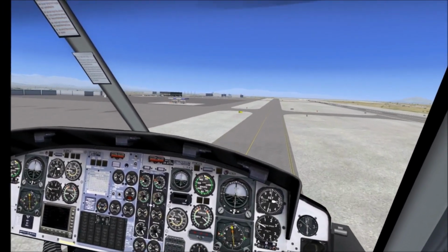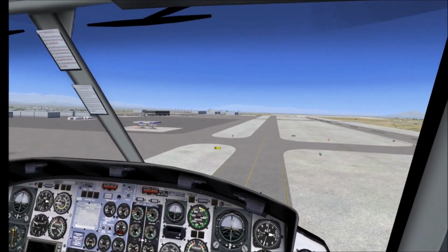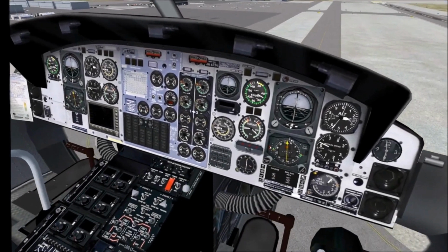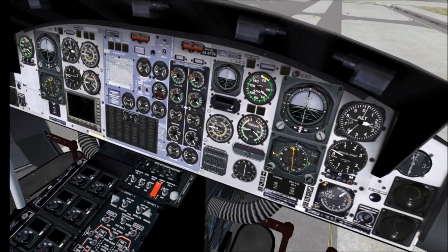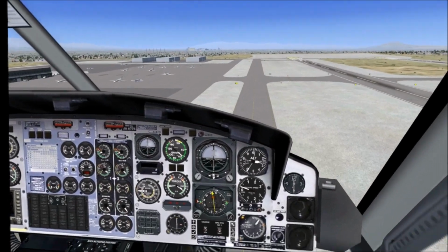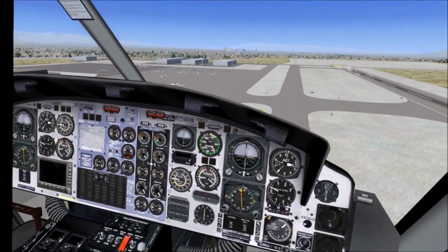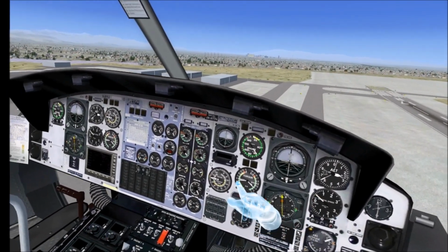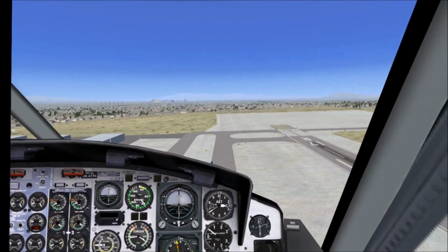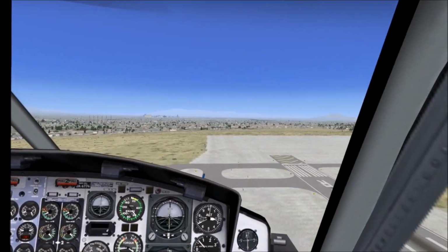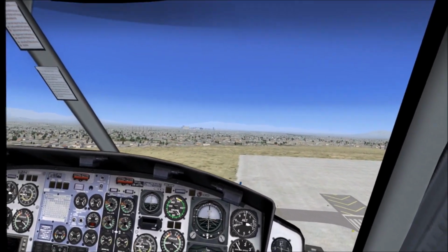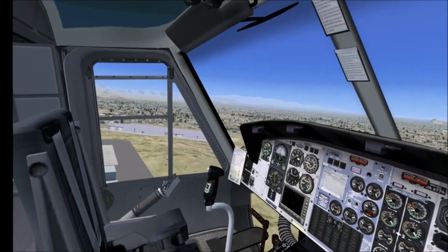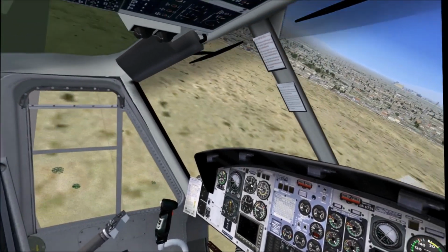So yeah, I'm not getting all the physical signs, which isn't uncommon for a simulator, to be perfectly honest. But for takeoff power, for IGE hover power, I've got a positive rate of climb. So I've got an acceleration, and I've got a positive rate of climb. All of that with takeoff power. So, not takeoff power, but IGE hover power. I can't argue against translational lift because the model is doing what it's supposed to.